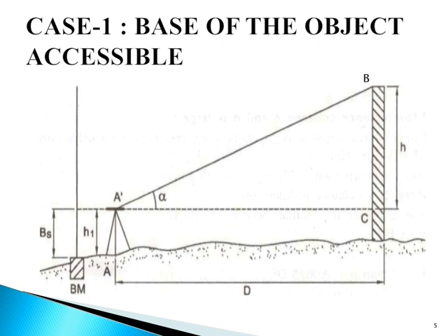Next is HI, capital HI, the height of instrument. Here BS is the reading of staff kept on the benchmark, where BM means benchmark. And alpha is the angle of elevation, or say angle BAC. So these are the main important terms.